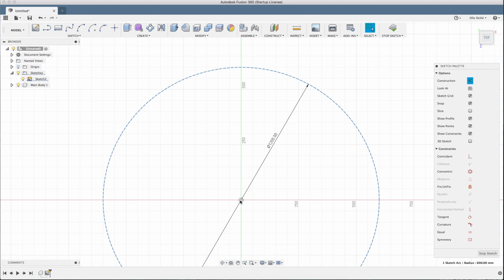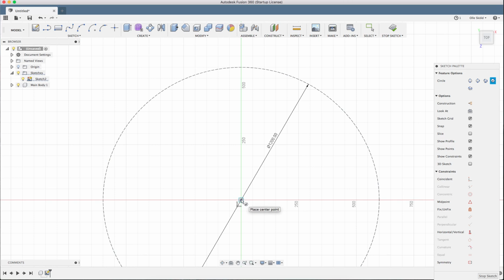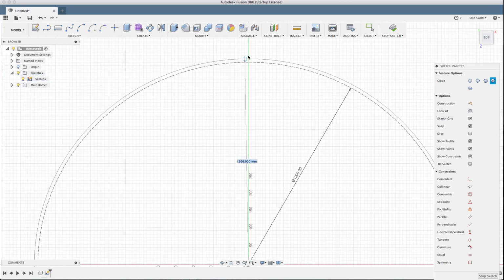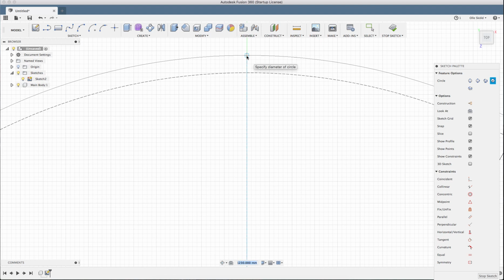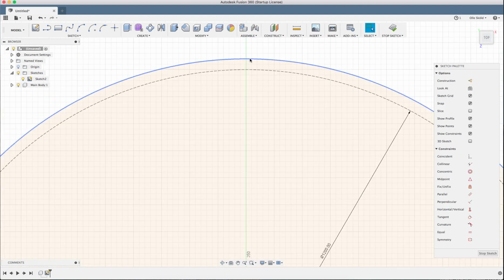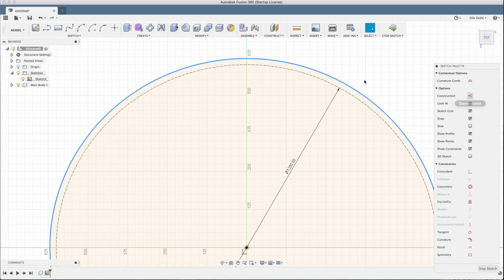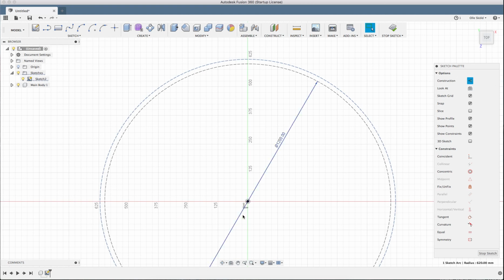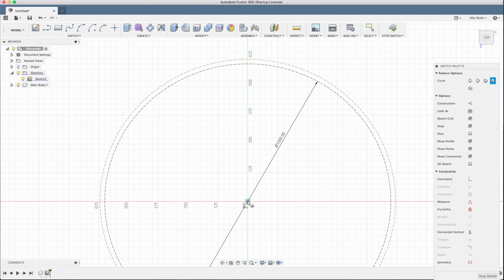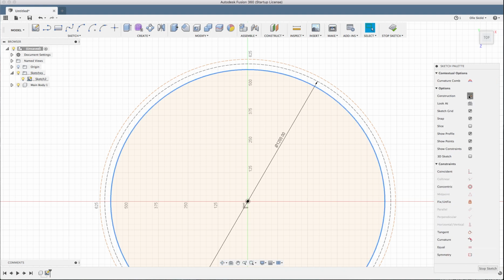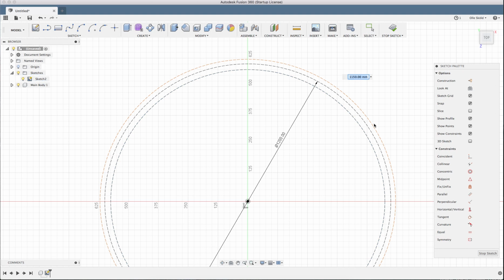And from that, I click C for circle. I apologize for that. I use these quick commands a lot, so I'm just clicking them without thinking about it. And C again. And I'll make 3 lines here. One is the center line, and one for the inner edge of the track.